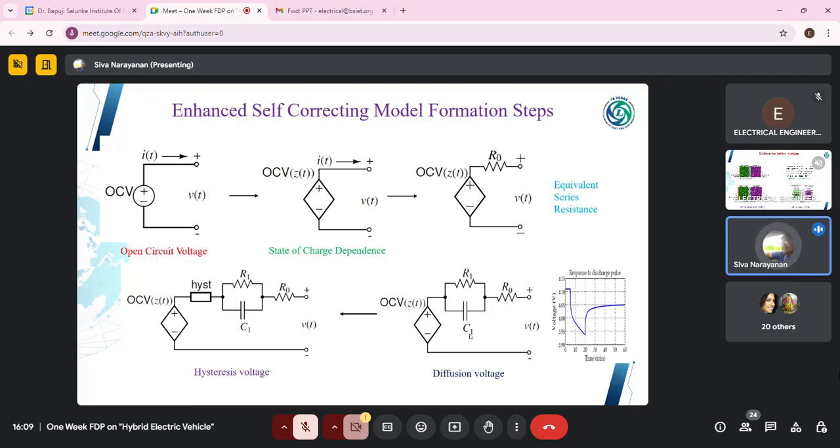Only if there is a resistance, you will have voltage drop across the load. So this concept they incorporated and they added the term R naught, and it is called the internal resistance of the battery. So it occurs naturally. There is no resistance connected to the battery.